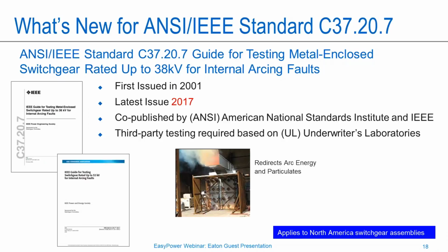This standard is really a test standard, and it defines testing engineered assemblies, power distribution and control assemblies, based on an internal arcing event. The premise or the basis of this standard is really to protect workers that are standing in front of or around the perimeter of a piece of switchgear or motor control assembly. Again, not unlike the arc flash testing in the 1584, there's a trigger wire that's defined in this test, and so you establish an arc event inside the enclosure.